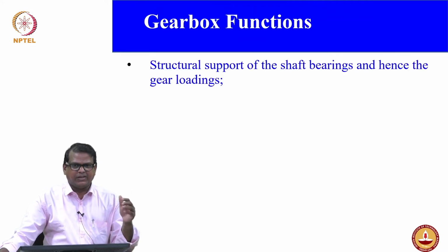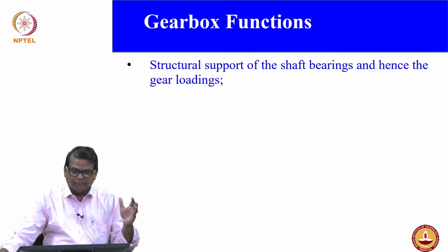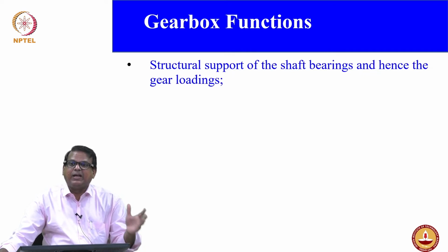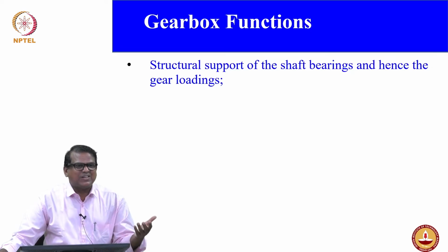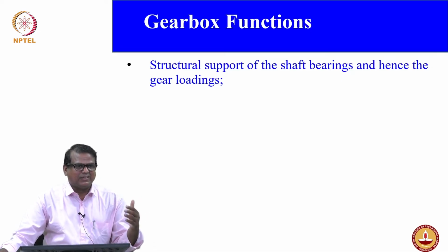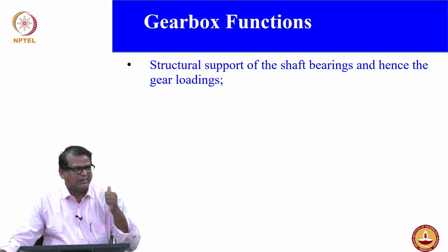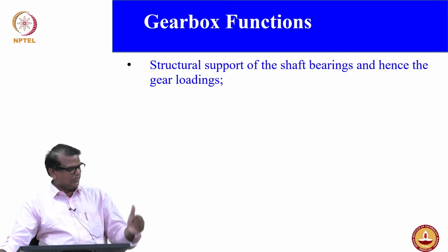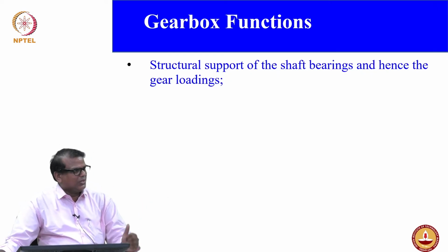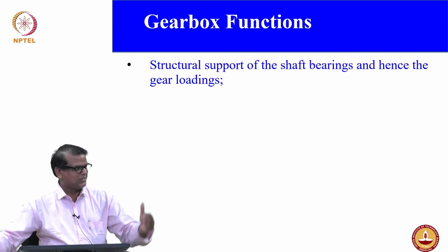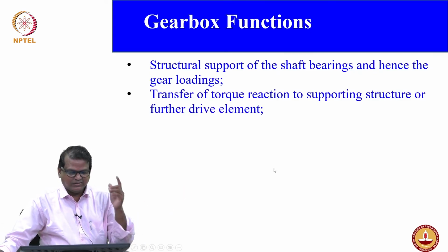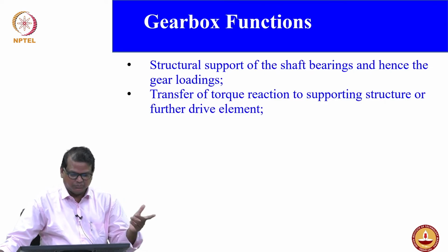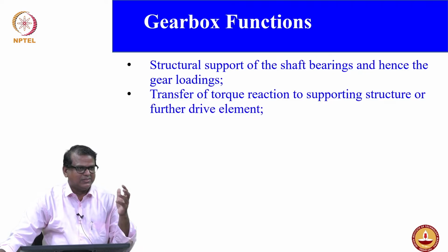When you talk about gear function, it provides structural support for the shaft, bearing and the gear loading also. So we always thought the gearbox was only for the speed aspect. No, it is not only speed, it should also be able to support the entire structure, that is one thing. It transfers torque reaction to the supporting structure or to the drive element. Okay, so this is the reason.